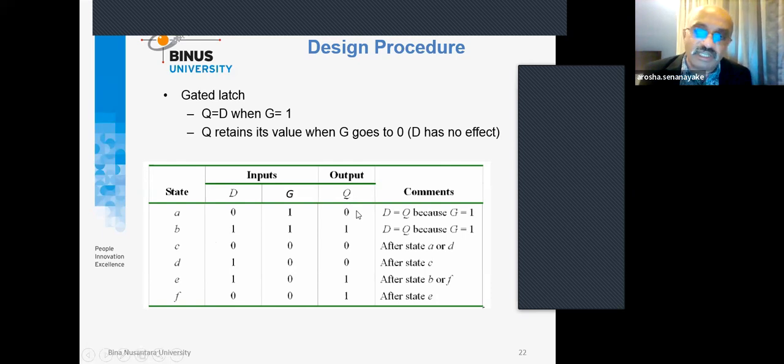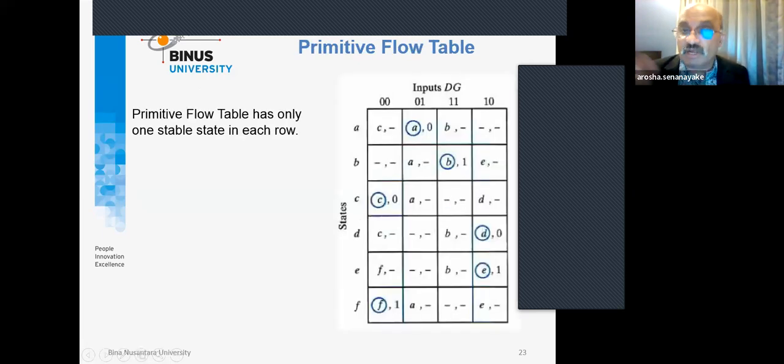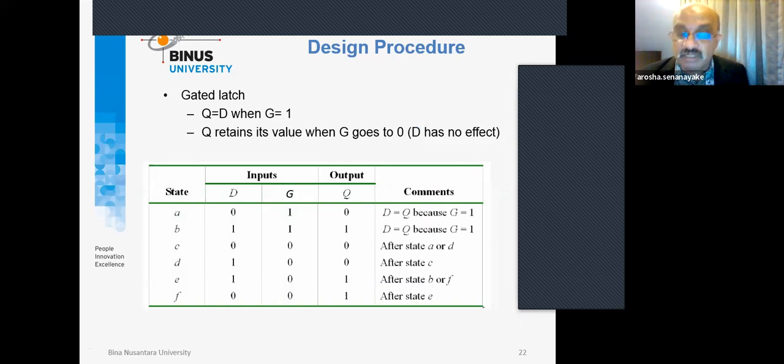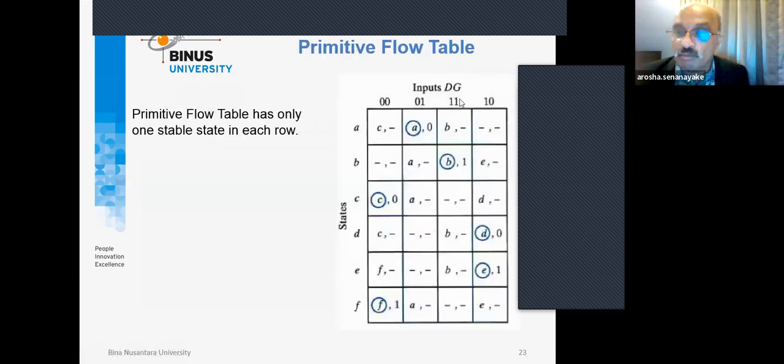Also, of course, we can take that. So that's how you can fill it, 1, 0, because in that case the state can be any state. So I will go through that one as well. While we are in A, if the input becomes 1, 0, what is going to happen? You can see that 1, 0 means these two, so that means we can take D and E, and the output change also to 0 and 1. So both are don't care conditions.